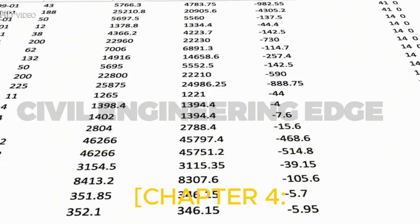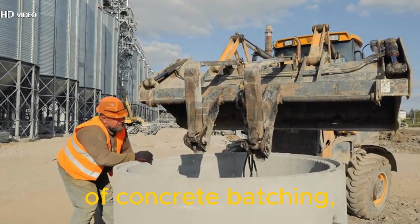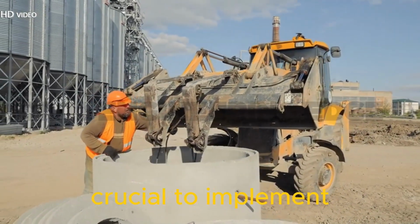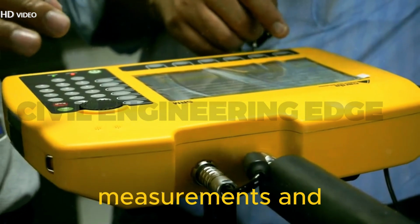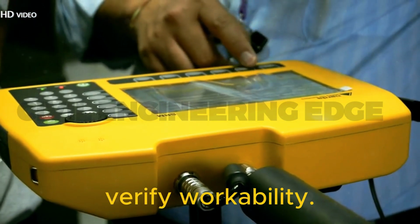Chapter 4, Practical Implementation. Visual: on-site footage of concrete batching, mixing, and quality checks. Now that we've designed the mix, it's crucial to implement proper batching and quality control on-site. Always ensure accurate measurements and perform slump tests to verify workability.